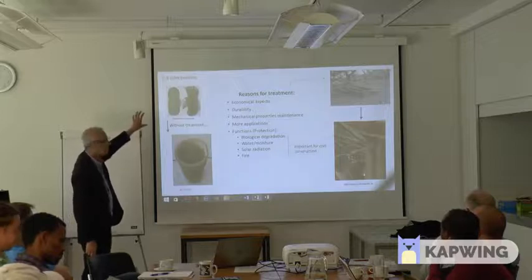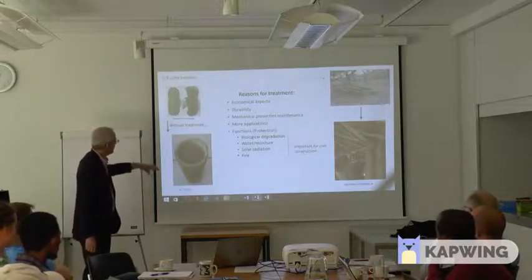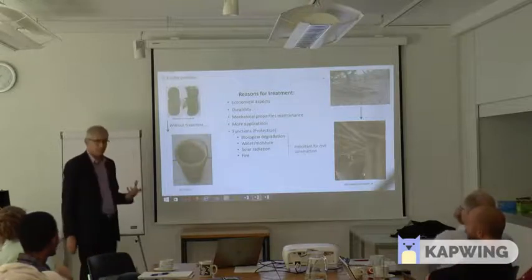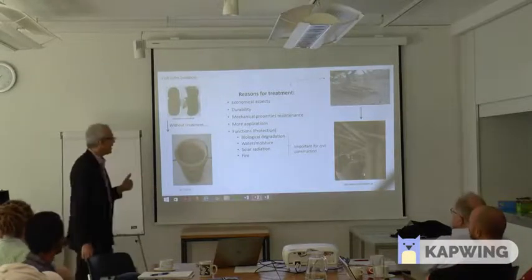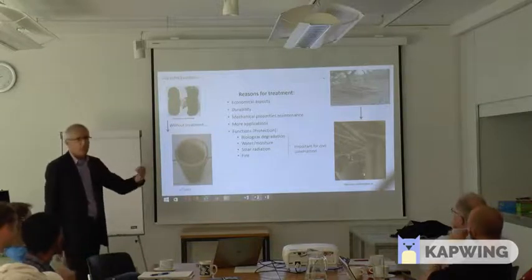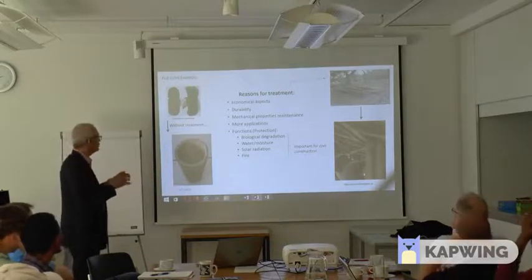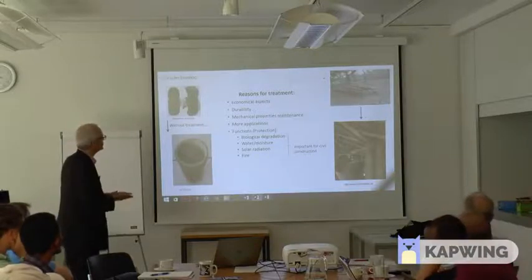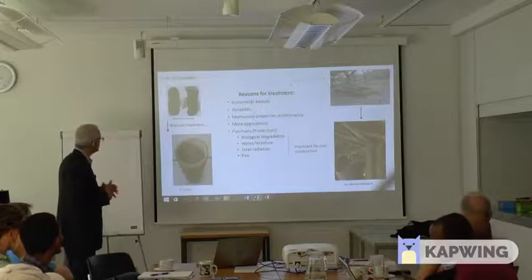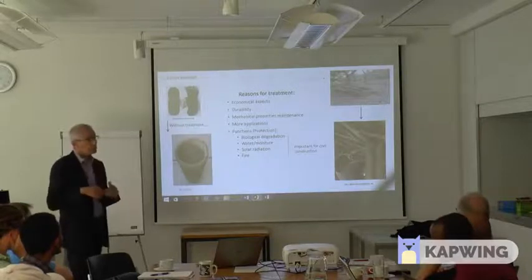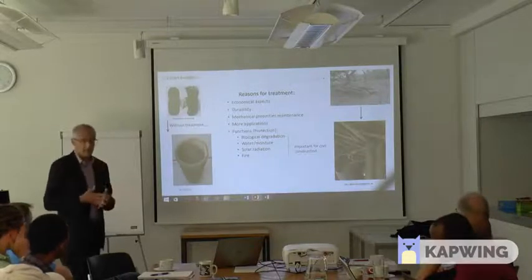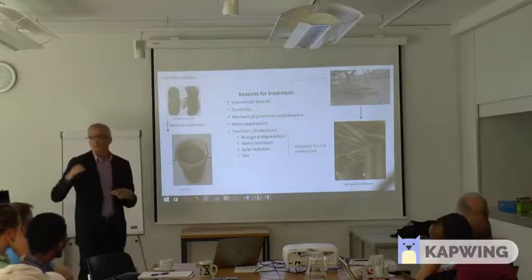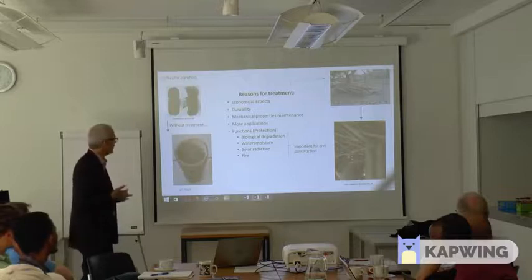It's a kind of beetle that can cause big degradation of the material after just a few months. So you can use it for temporary construction, but for permanent construction it would be a disaster to use a bamboo culm, for example, because the degradation is very fast, especially in humid or high temperature environments.